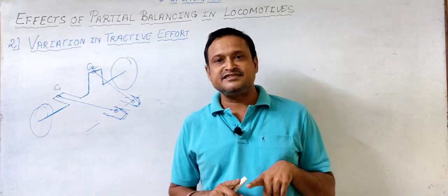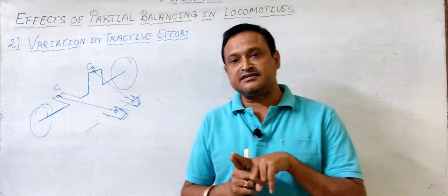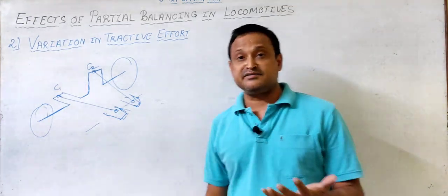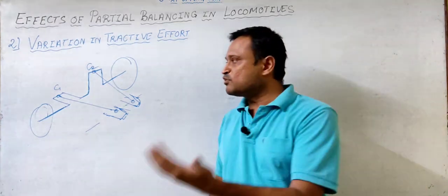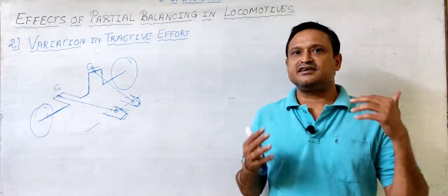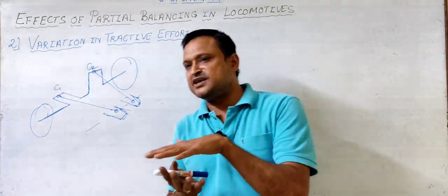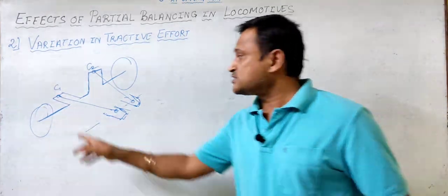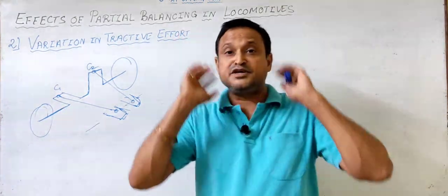And when the transmission angle is 0, the torque required to overcome that situation will be very high, right? So say, for instance, a locomotive stops at a place and incidentally the situation comes out to be this, then the torque required at this shaft will be too high.